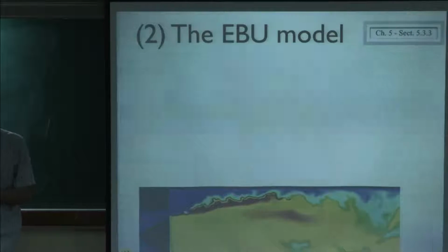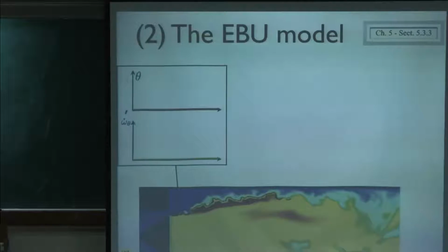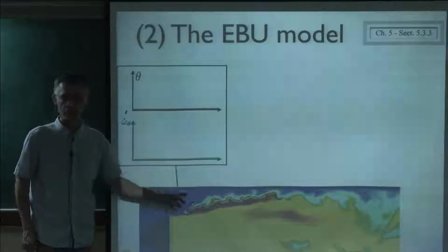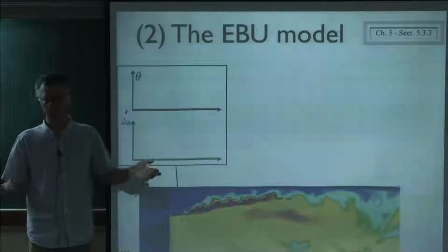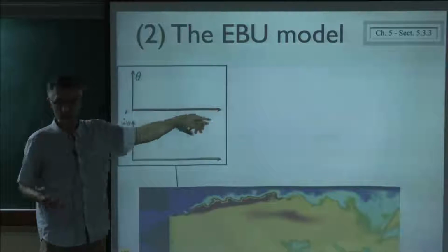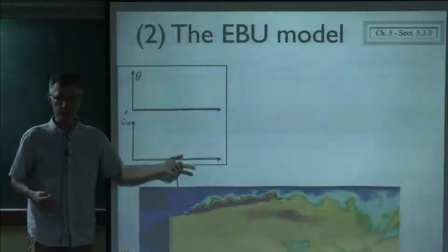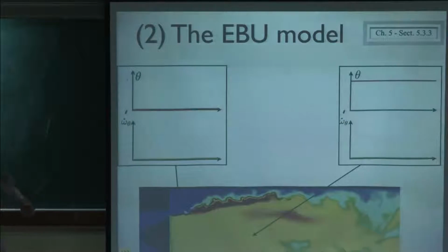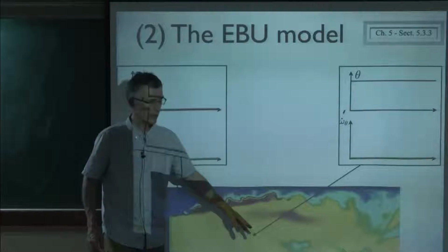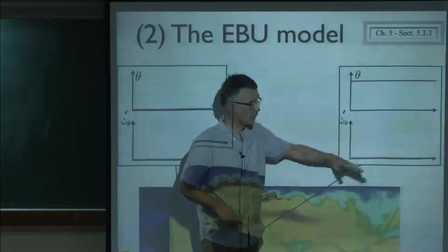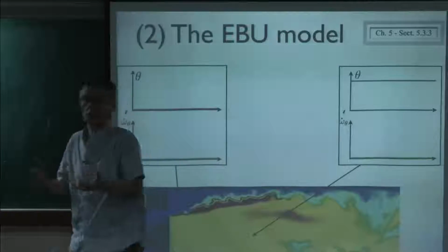So he said, okay, if you look at a flame like this one, and you take a point here in the fresh gases, and the flame never goes there, we know that the reaction rate will be 0. Okay? So if we plot the temperature it will look like this, 0, and the reaction rate will be 0. Nothing, the flame is not there yet. If we take a point in the burned gases, and it's fully burned, here the temperature will be 1, everything is burned, and of course the reaction rate will be 0 because there is no fuel left.